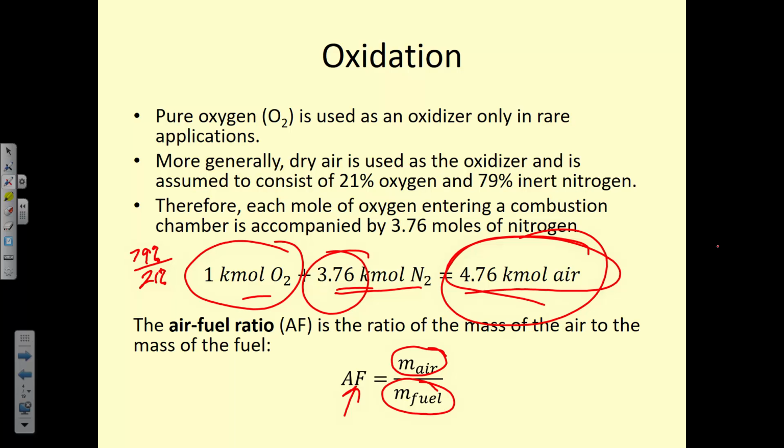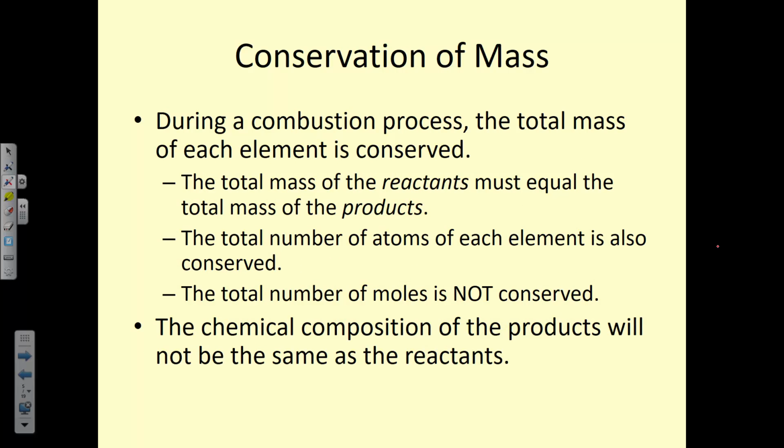There are some cases where, if you have too much oxygen in the environment, the combustion occurs too rapidly, and it's also an incomplete combustion, because certain products burn up quicker than others, and then others are exhausted in the exhaust.